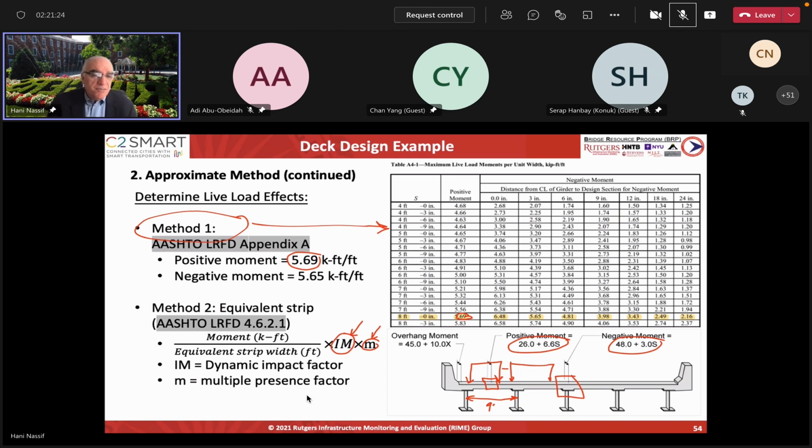So that means there are so many bridges at about 20 years, and some bridges are 45 years and 60 years, especially the less traveled bridges. And so ADTT, the number of trucks on the bridge, and the level of overweight was a big factor in reducing the lifespan, the service life. So decks need to be more resilient, because that's the first line of defense. This is where all the trucks, all the heavy loads are coming in.